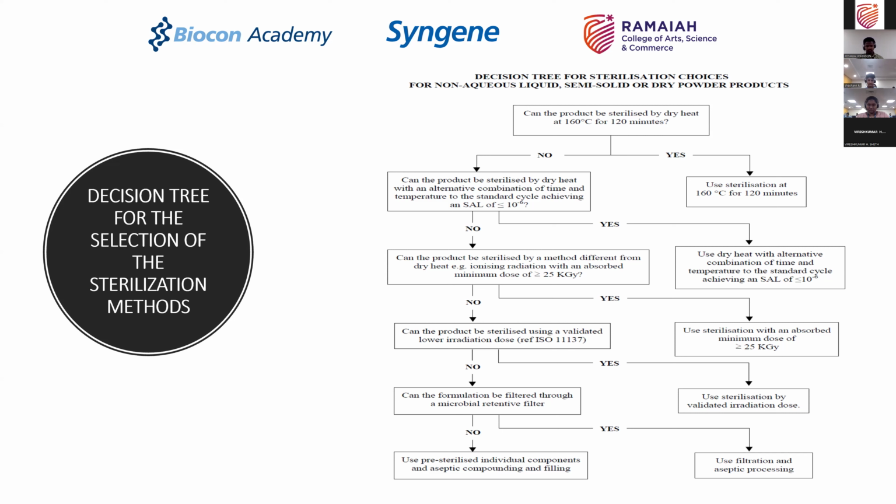Because with dry powders, what you could do is dissolve it in a liquid media which is filterable. You filter that media so that any microbial particles get retained on the filter, while the powder which is dissolved in the liquid passes through. And then you precipitate out the powder after filtration using sterile techniques or aseptic processing techniques, and therefore you get a powder post that.